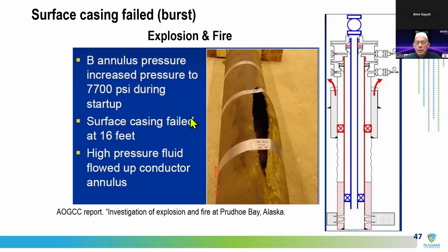But for offshore, what we do is on all the casing annuli, we have a gauge valve. We open the gauge valve so the pressure will be read up here. Normally we put a pressure gauge of, for example, 2,000 psi. If the pressure goes up beyond 2,000 psi, it will break the gauge, so it automatically becomes a relief valve.